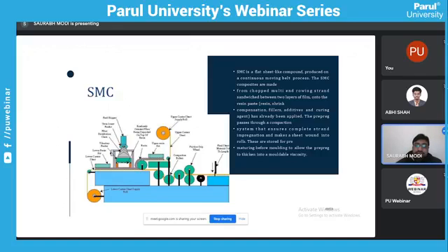See, it is produced on a moving belt process. They are made of chopped strand mat, what we discussed initially, and roving strand sandwiched between two layers of film of resin paste. So here the resin will be your matrix, and chopped strand mat or roving will be your reinforcement. You can add different fillers, different additives, different curing agents to make this process a little bit faster. So this is the whole process.